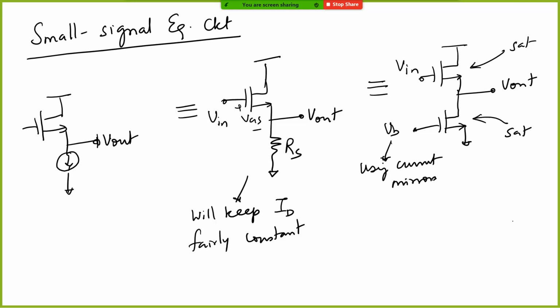All right. So by using this, you can basically bias this, and of course, any real current source will have a current source and a shunt resistance. The same is the case for this. And all the things that we looked at earlier, like you can have a single transistor current source. You can also have a cascode current source if you want. So all that works well.